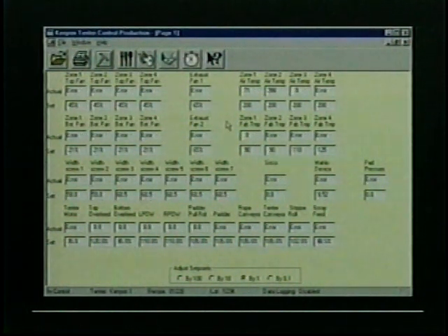What you will see on our screen, since this is a demonstration and we don't have enough devices to fill the screen out, is that you will see error in the actual value of a lot of the devices. What the error means is that this device did not communicate back with us. Therefore, error is proper. In your system, if you see error, you will have a problem and you will need to call maintenance. It will mean that the device is either not functioning or communicating, which is an indication of a problem.